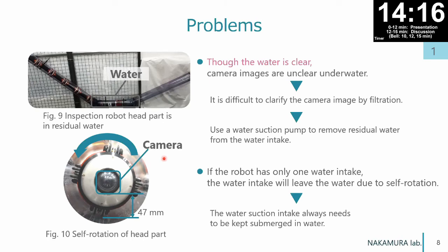Okay, if you were using ultrasound, it would be advantageous to have water in the pipe, wouldn't it? Because then you would have a couplant to couple your ultrasound to the pipe wall. You could look for cracks that are maybe even hidden.